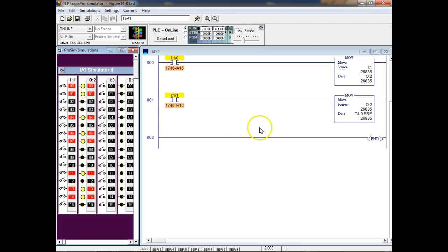So what I did is I read this input port, I read this output data file, right? You understand? Y'all understand outputs are a data file, right? And then we set ones and zeros inside a data file, and then what happens is our what? It just masks this, right? Do like output 2/0, 2/1, and then only light up one of them.